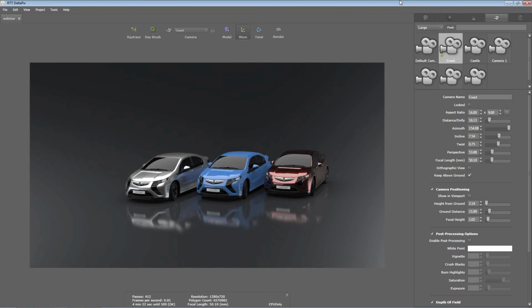Now, there's a question that says, saying that we use CUDA, will it be better with a GeForce 590 that has double the CUDA processors? In general, we are not recommending the GeForce over the Quadro graphics cards. This is not related to counting the CUDA cores of the card, but it's related to, for example, the additional functionalities and the driver support that we have for the Quadro graphics boards.